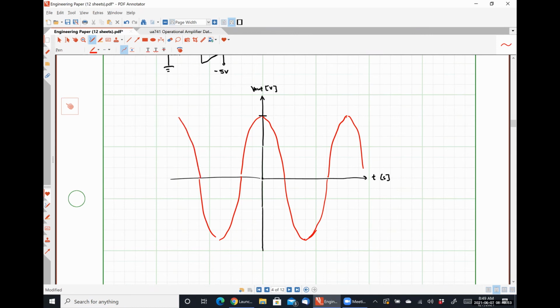All right. So this is positive 12, and down here is negative 12. With saturation distortion included, this is positive 10 volts. So what we would see is that our output signal cannot exceed that value, and negative 5 volts would be right here.